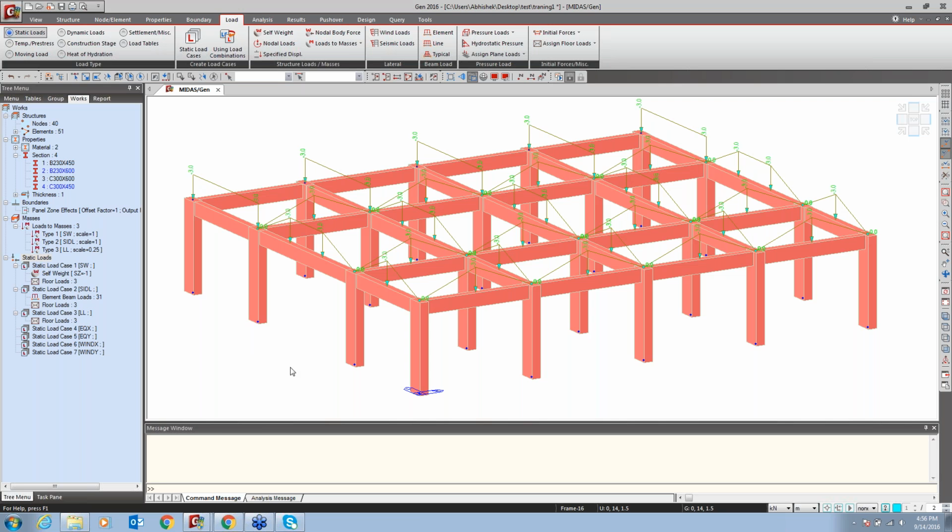Yeah, for the cantilever you have to model the slab, because that cantilever is connected with the backside of your beam. So you have to model the slab based on the FEM analysis, and it will take all the moments and everything into the connecting beam. Otherwise, you can directly apply the loading to the connecting areas. So this option is also available.